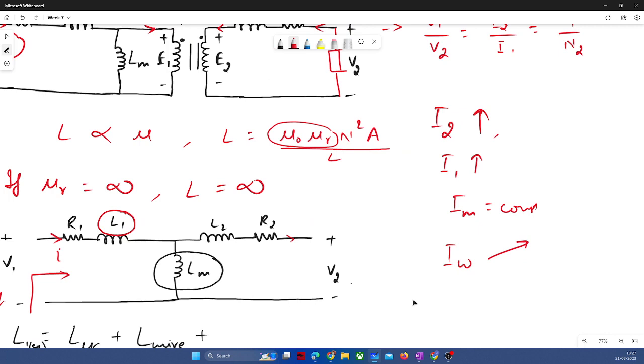Not all the amplitude of the working current will go into losses. A certain proportion of that current will go into iron losses, and one additional loss will be there, copper loss. When you have significant current and you have winding resistances, you will have some losses in the winding resistances, and that will be copper loss, plus core loss, and whatever load power is required.